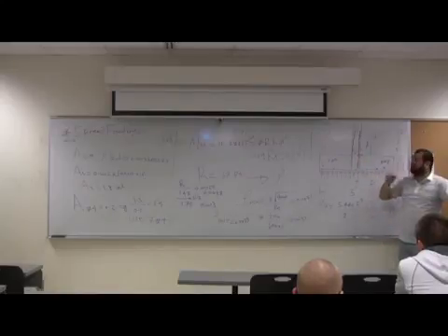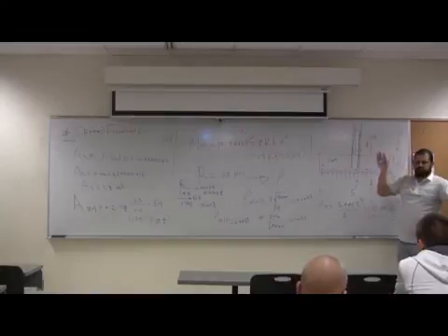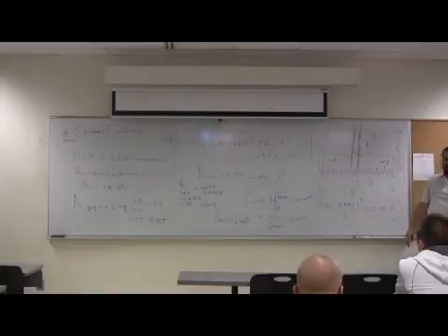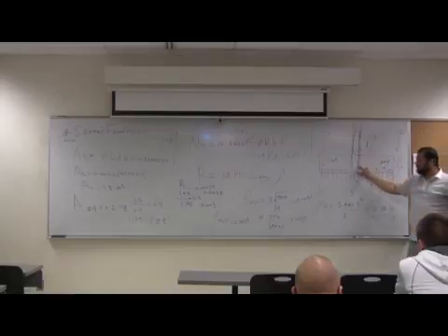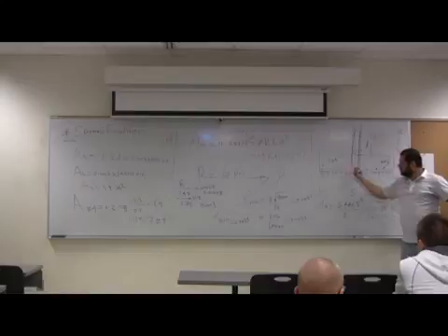Development. So you calculate the development length for this bar with the conditions you have: normal weight concrete, not epoxy coated bars, the size of the bar, it's not top or bottom, all these coefficients. Let's say you needed like 30 inches. Is this enough or not? If not, you go hooked. You hook this one to this side, this one to this side, so you have enough within the footing.